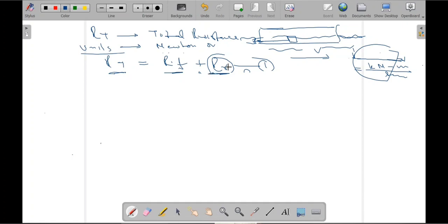And that is why, in order to reduce this factor, you must have seen we use the bulbous bow in many cases. This is only for the purpose of RR, residuary resistance, to reduce this residuary resistance for fast moving vessels. Although by providing this bulbous bow we are adding a little more wetted surface area, so we are adding a little more frictional resistance, the benefit of reduction in wave making resistance is larger, and therefore we get a benefit by using this.